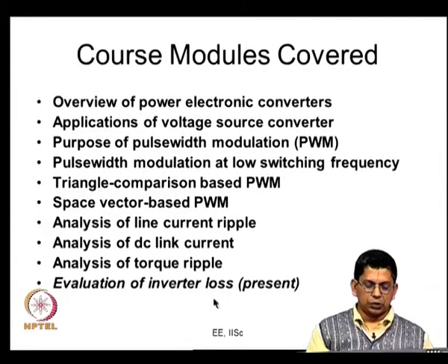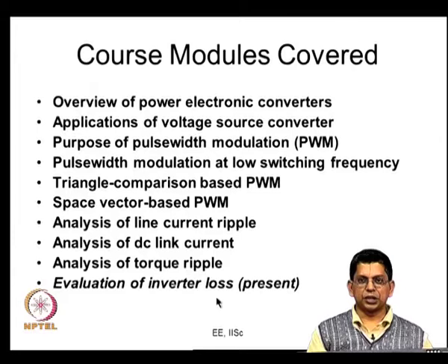When there is a switching transition, there is a certain amount of power dissipation, some amount of energy loss. In the first lecture in this module we focused on the conduction loss, and in the second lecture we focused on switching loss.